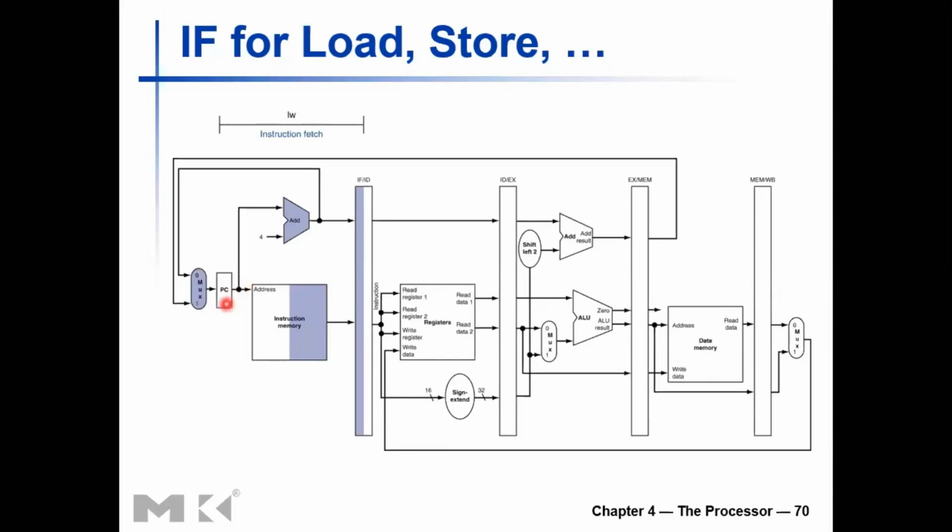with the up-to-date program counter value, you read it, and the reading is also going to take some time. The newly updated value has to propagate outside the register, and that will take some time. Once that value is taken out of the program counter register, it is connected to the instruction memory for you to read the next instruction. The address is provided to the instruction memory. Usually it is the address following the previous instruction, unless there was a branch instruction in the pipeline.